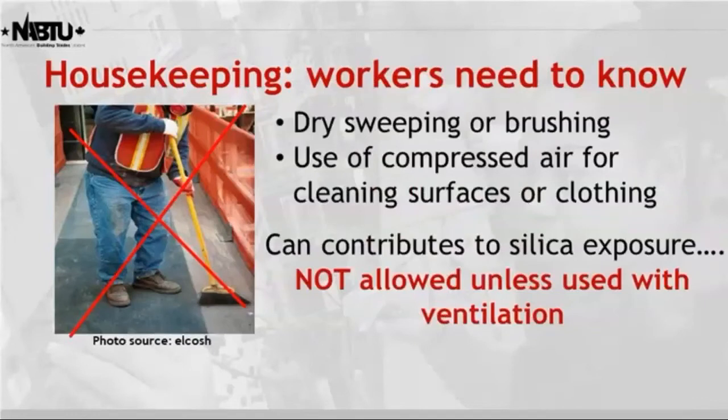Going back to housekeeping, dry sweeping, for the most part, is not allowed under the new standard. If you're going to sweep up following the activity, ideally you would use something like sweeping compound. Perhaps you can use one of your vacuum systems to vacuum up the dust. But what you don't want to do is use compressed air, because you're just going to blow it back up in the air.